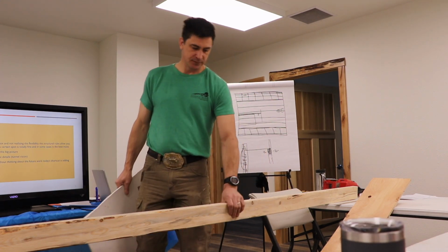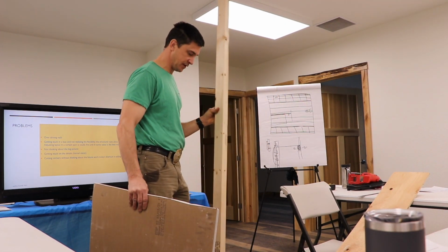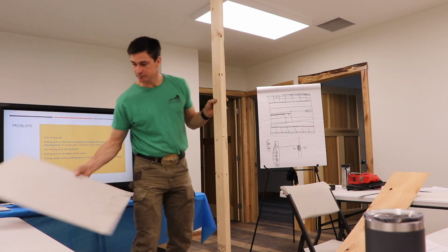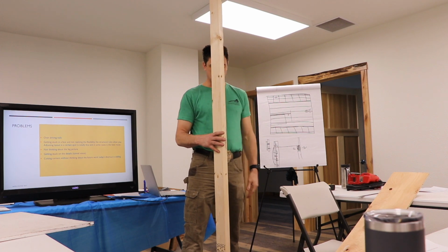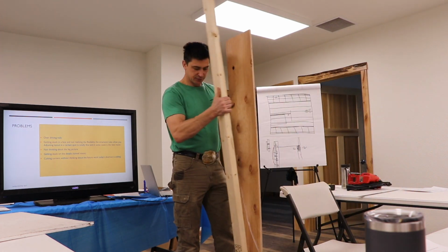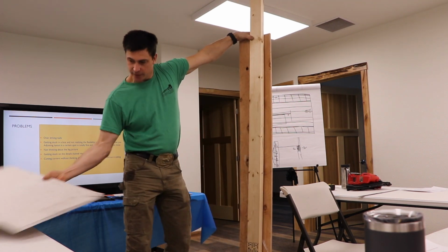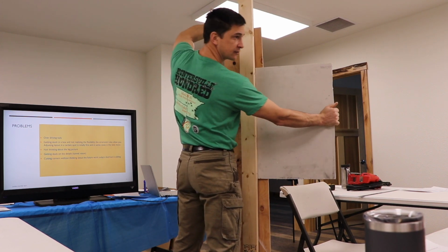All right. Guess we have a ceiling up there. Let's say this is the end stud, and here's my outside wall. Typically guys would put some kind of backing in here so that when I run this sheet of drywall, I have backing I can screw it into.